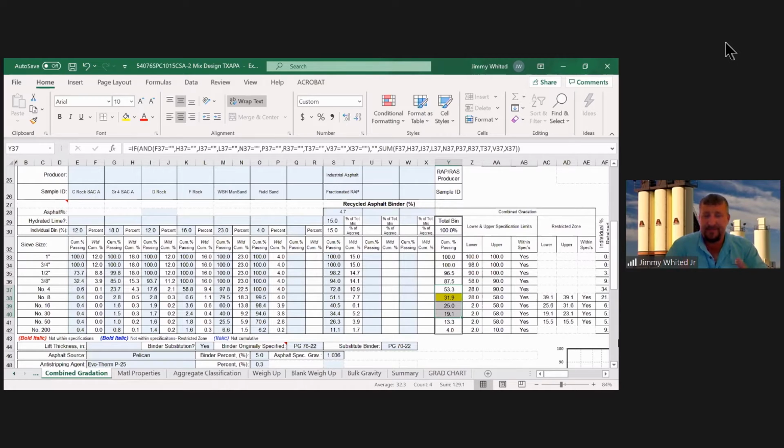When this happens, we automatically know, hey, today we're going to have to add a little more sand because our moistures are 8%. Let's bump that sand up 2% and take it out of here just for our first sample. If it doesn't work, we'll change it back. Having a good, strong QC department that works with the plant is pretty vital in this case.